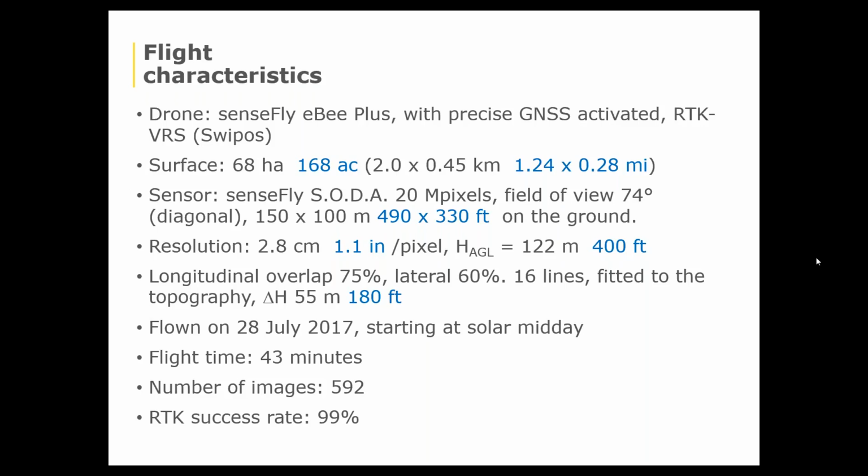592 images, nice flight, and very important, the RTK success rate: 99%. It means that we are almost perfect. You will see that out of these 500, almost 600 images, only 6 were not with the highest accuracy.